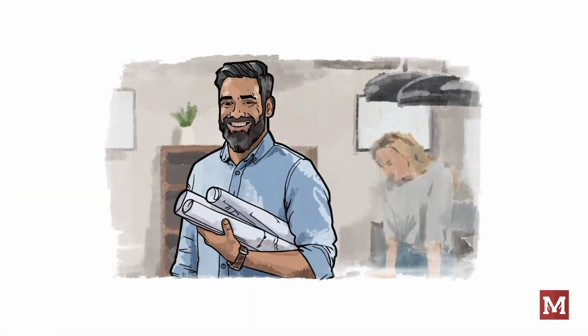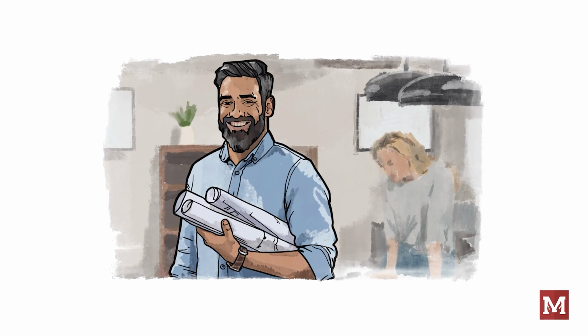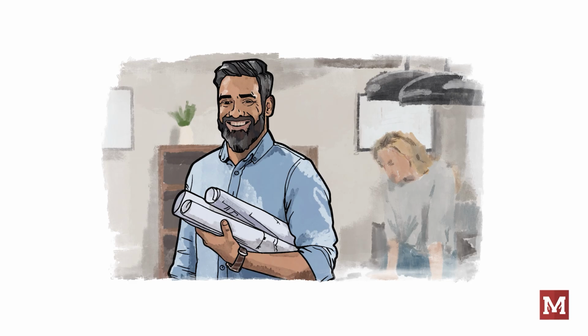In this segment, we explored how to read building plans. We discussed the title block pages and the information therein pertinent to your design work. We talked about the different drawing types and what information there we need to understand for the design process. Finally, we talked about the importance of keyed notes and text notes as well as the big picture overall.